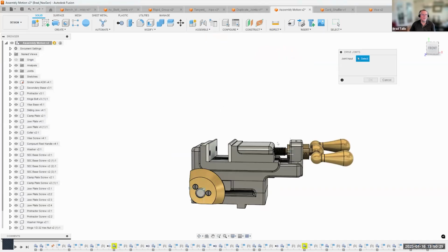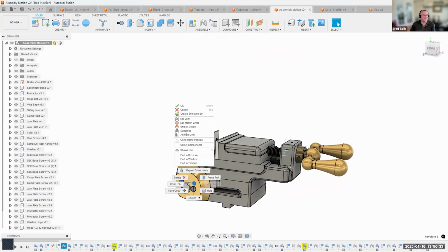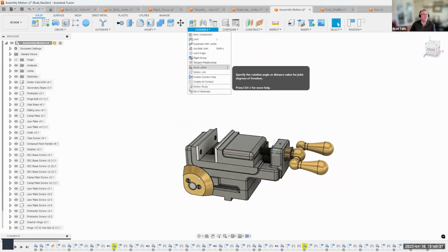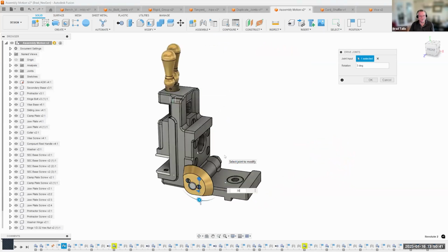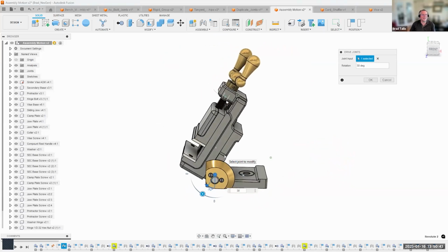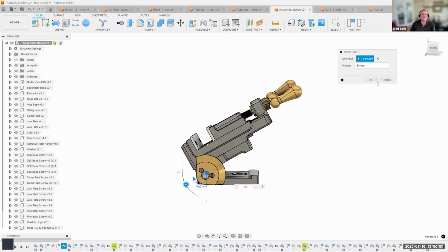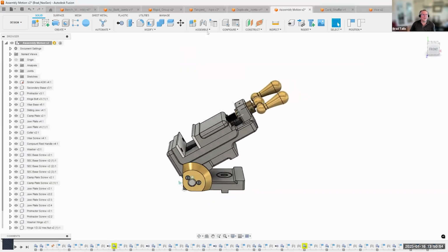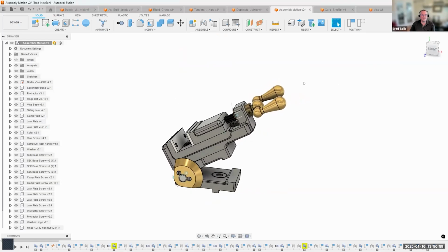Drive joint. Oops, it locked it back up. Give me a second here because I said undo. I'll go ahead and say drive joints. Let's set that to be 30 degrees. And now that's set to like 30 degrees, for example, or 60 degrees, whatever you want that to be. And you know that that's precise, right? So kind of a cool trick. Not a lot of people know about that, but that's what that drive joints allows you to do.